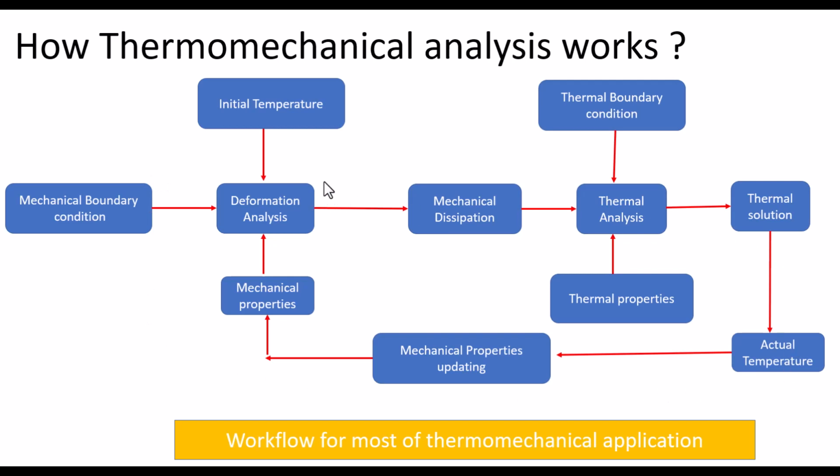That is a strong way and the weak way. And I just want to highlight that whenever we are splitting the thermal analysis and transferring the result, that is normally called a one-way coupling. So there can be one-way coupling, two-way coupling, and inside the two-way coupling, we can further classify based upon the naming convention given by the solver: the strong and the weak coupling method.